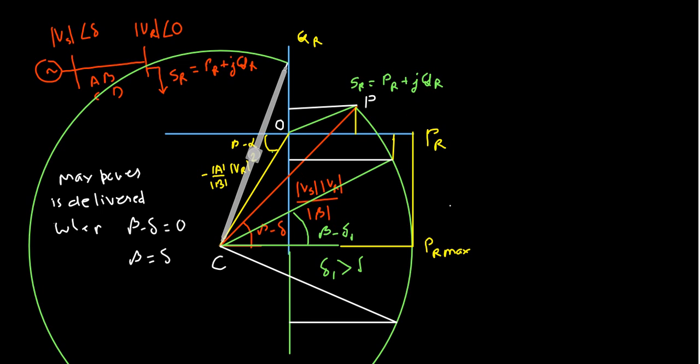So we will see in the next lecture that you have to use some compensation devices if you want to serve the PR which you desire, and the QR you have is something different than the QR given by this locus. Then that much difference between the existing and the one given by this locus must be additionally employed at the receiving end. So we will see with the help of some more examples the circle diagram.